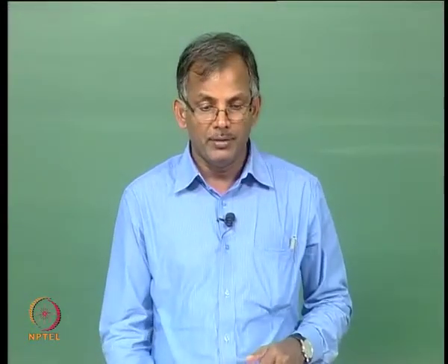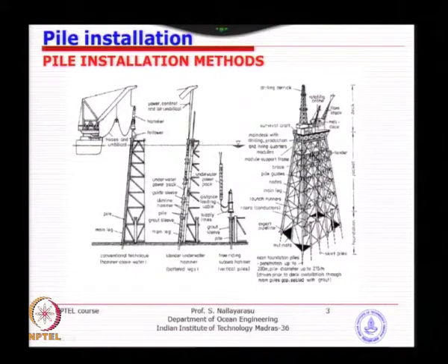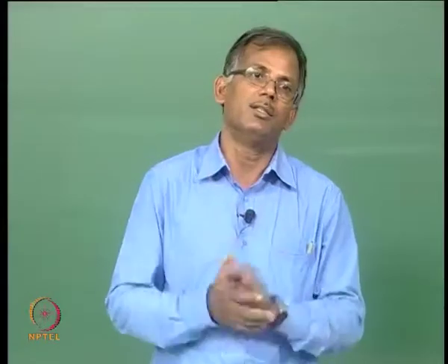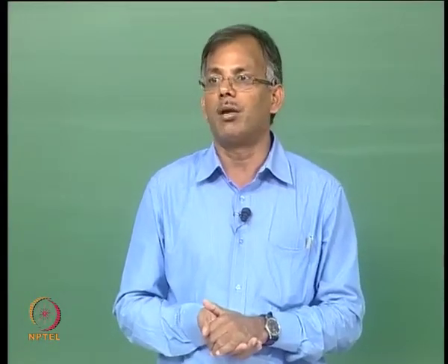Then you determine what height is required, because if you assume too much penetration or softer soil, and it so happens that it does not happen in the field, too much length will be sticking out and you can't put your hammer there because the pile will fail. So, you have a difficult problem to solve. That is why we need to find out each of these categories, the upper bound side and the lower bound side, and make a decision, a calculated risk, take a certain height and make the length of the pile, because once you bring the pile you cannot modify it, you cannot go and cut, because each time you cut it takes a lot of time.